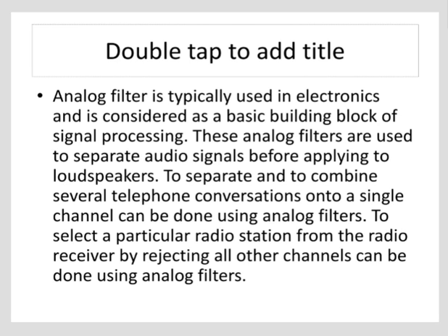It is wise to apply an analog filter prior to the signal conversion so that all unwanted frequencies above or below where the desired signal is reasonably expected to operate are removed.